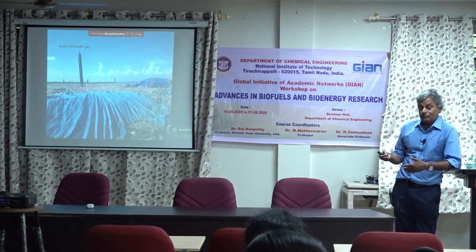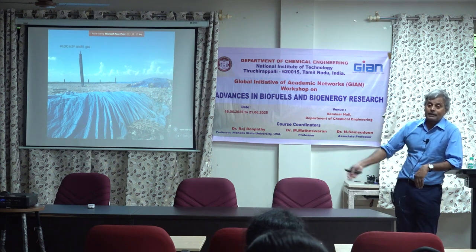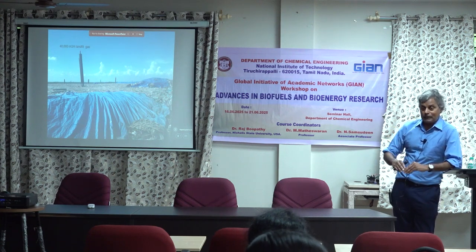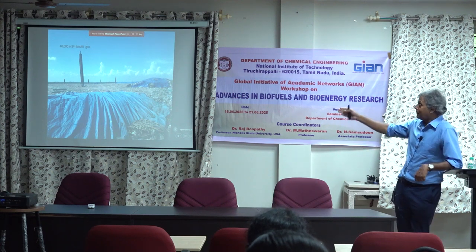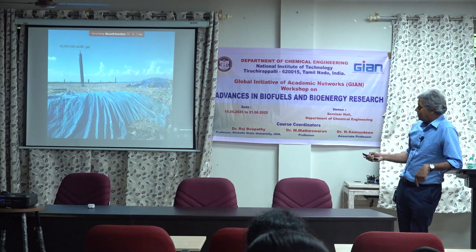Okay, so this is the best way of closing the loop. So gas is not going up into the atmosphere causing greenhouse gas. You are collecting the gas and using the gas. So again, it's an anaerobic digestion concept. It's a solid, high solid anaerobic digestion. Okay, so that's what they do in landfill. They collect the methane, purify the methane, and sell it.